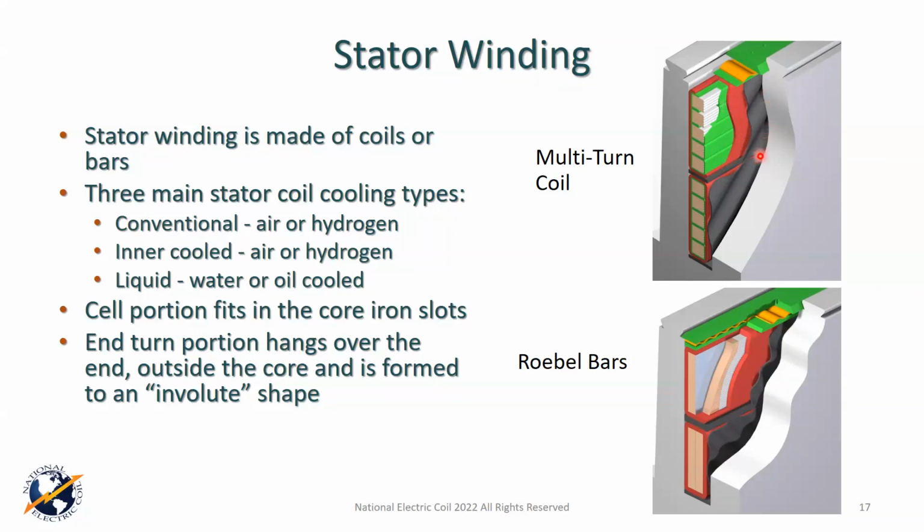I would hope you would agree that the one most likely to pop first is the one with the greatest pressure, the 20 pounds. In the balloon, it was the air pressure against the balloon wall that allowed it to fail. In this case, if you have very high voltage stress on the ground wall, a high volts per mil, high VPM, that's likely to fail before one that has a lower volts per mil.